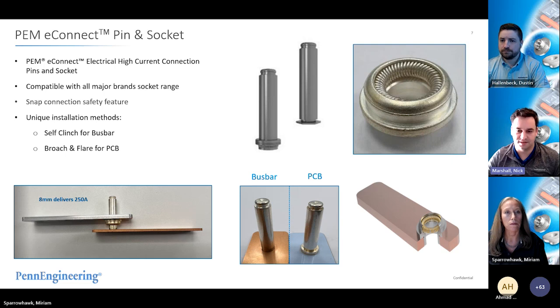So we're removing the need for additional loose hardware or assembly steps for other headers, and we're pressing this directly into the bus bar where it's permanently captivated into that joint. Then we're doing the same thing on the other side, where we've developed the socket that you see in the top right, which has a series of coiled connective points, which are making the joint between that pin and the mating bus bar.